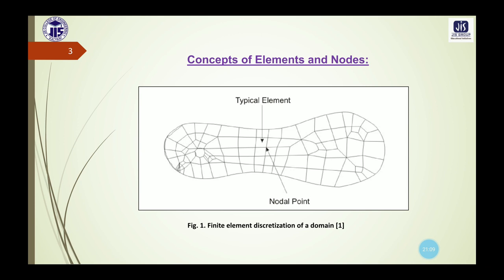Now, based on the application of this finite element method, the problems are classified as structural and non-structural problems. In case of the structural problems, the displacement at each nodal point is obtained, and by using these displacement solutions, stress and strain in each element can be calculated. So this is the concept of the structural problems.